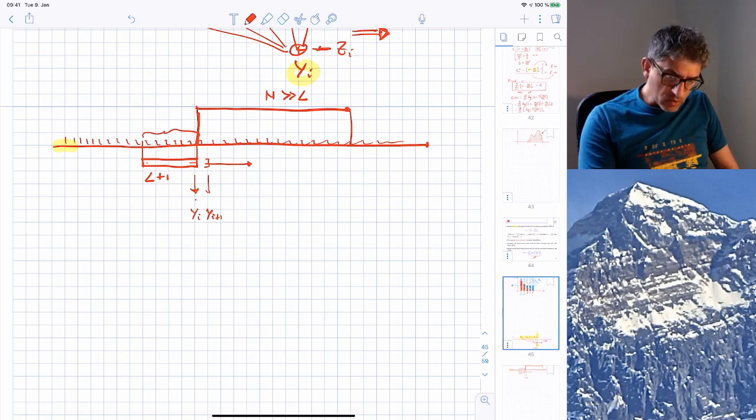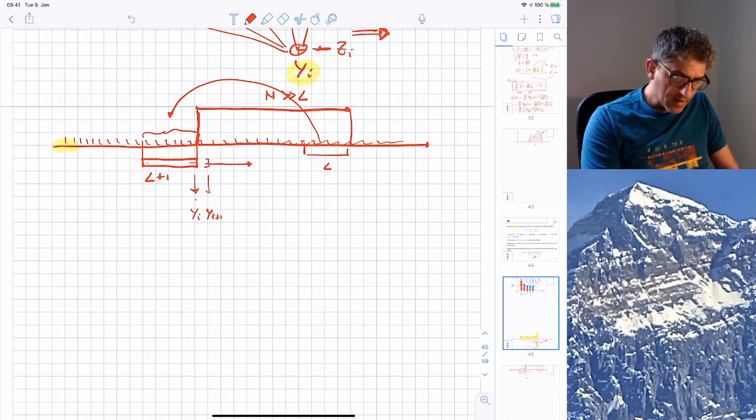Then I use the following trick. Instead of sending just the sequence X, I consider these blocks and I form the transmitted sequence by taking the last L symbols here and copying them in front. This is called cyclic prefixing. So for every block of n symbols, I create a cyclic prefix by basically copying the L final symbols to the beginning.